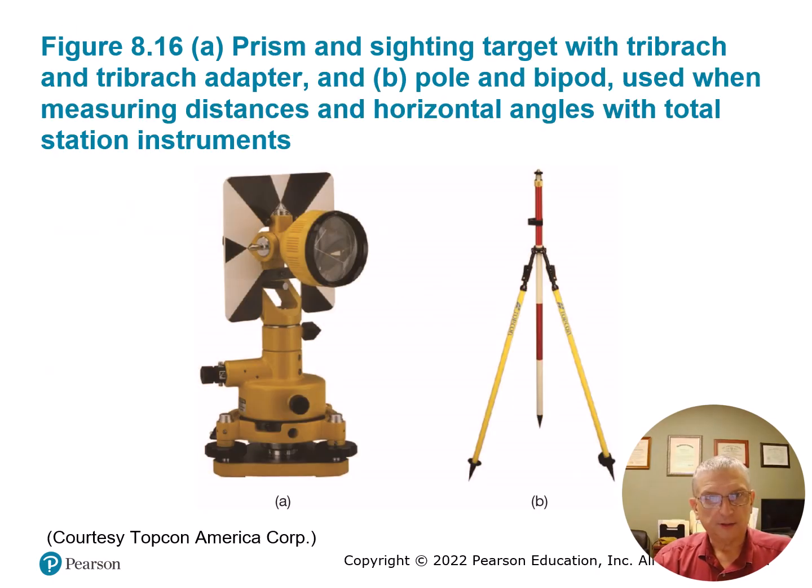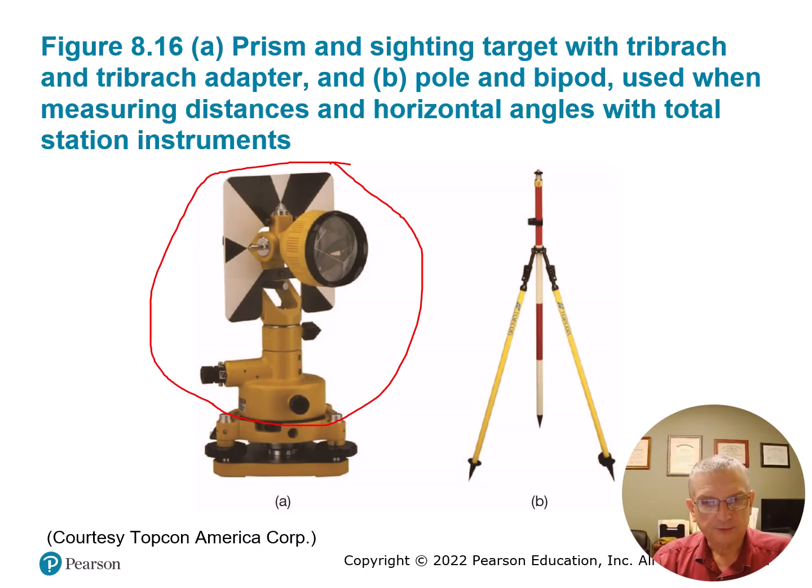Some of the equipment that's involved in total station, we talked about earlier, if you've got these target plates that sit in a tribrach, I've just circled it. These bases right here have the same 3 lugs that lock into the tribrach down here. It even has a collimator up here. Sure does, where you can point that right at the instrument so that you have a nice directly pointed prism and target plate. Notice that this has a nice point here that's horizontal that you would turn to for your vertical angle, and a nice one here for your vertical angle.